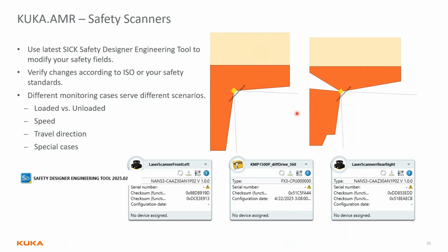There's also path replanning. So if the AMR waits for a long time and the obstacle doesn't move, it's going to try to find a path on the graph. It's not going to go around the obstacle. It's just going to go back and find another path. You can disable both of these.